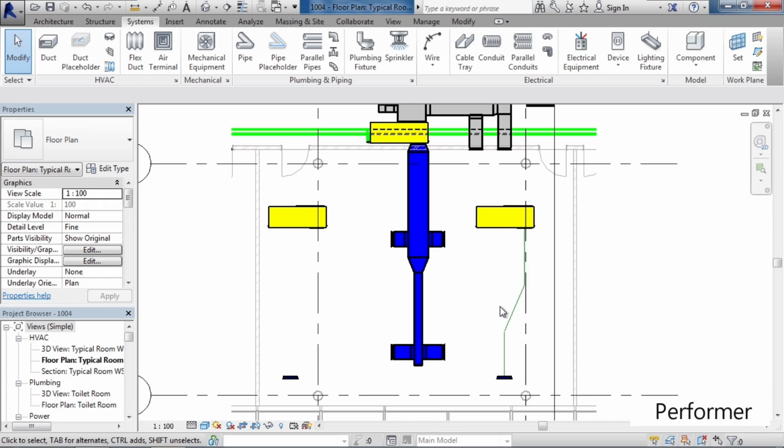Typically, it's used in conceptual design if you're just conceptually laying out that duct arrangement or that duct line. It still does connect to your diffusers and your air handling units. But the difference is it doesn't have justification values, simply because it's just a line. It also lacks information for insulation or lining, whereas a regular duct would have that information.